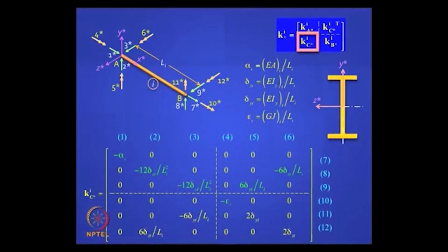So here, as you rightly said, alpha and epsilon get a negative sign, I have marked in green color, and here the shears are the diagonal elements, okay. So you get minus 12EI by L cubed, that is the only change, and in the 5th and 6th columns the shears will be 6EI by L squared, they get reversed. So think about it and please come prepared.